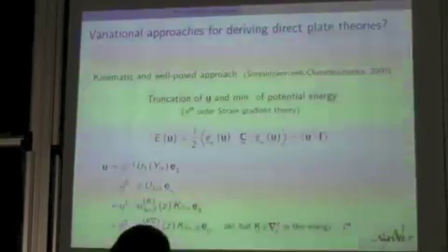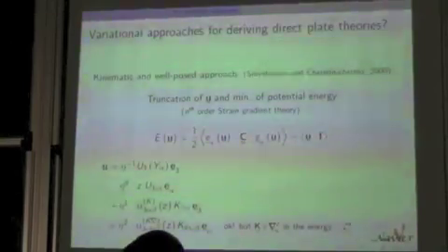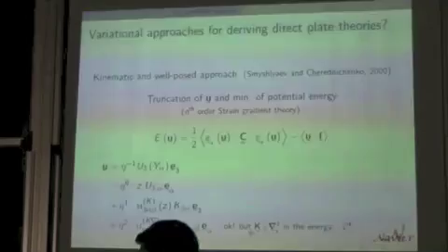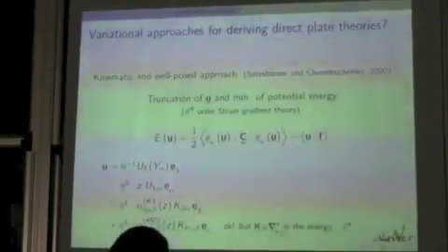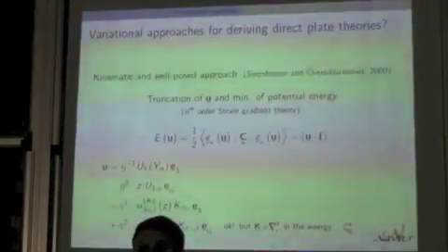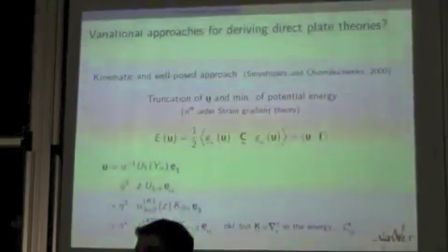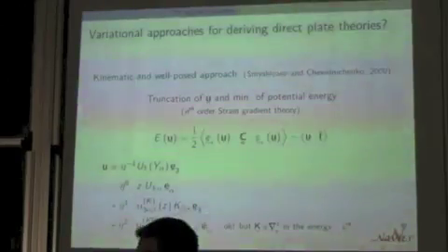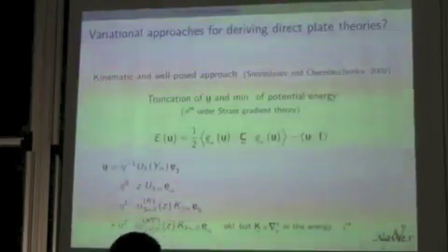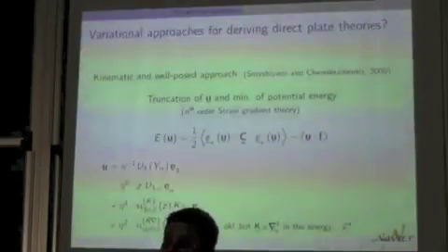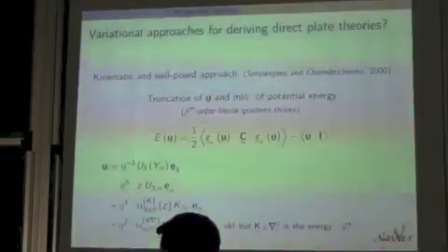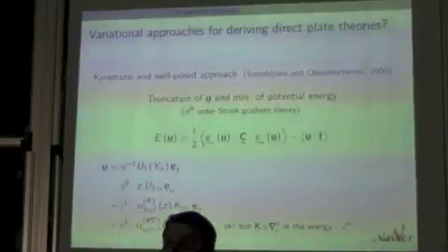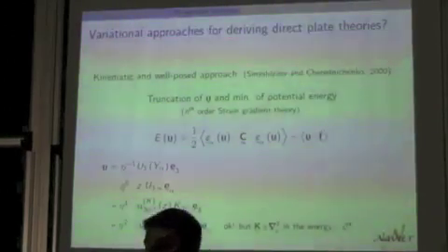If you do that, you're happy, you have all this displacement field, and if you compute the energy, you will have the second gradient of the curvature, meaning C4 regularity for the displacement field. Now the boundary conditions are just a bit better, but still impractical. So this is a limitation of a pure displacement approach, and we'll try to show you that if you have some other static arguments, you can build a very efficient plate theory.